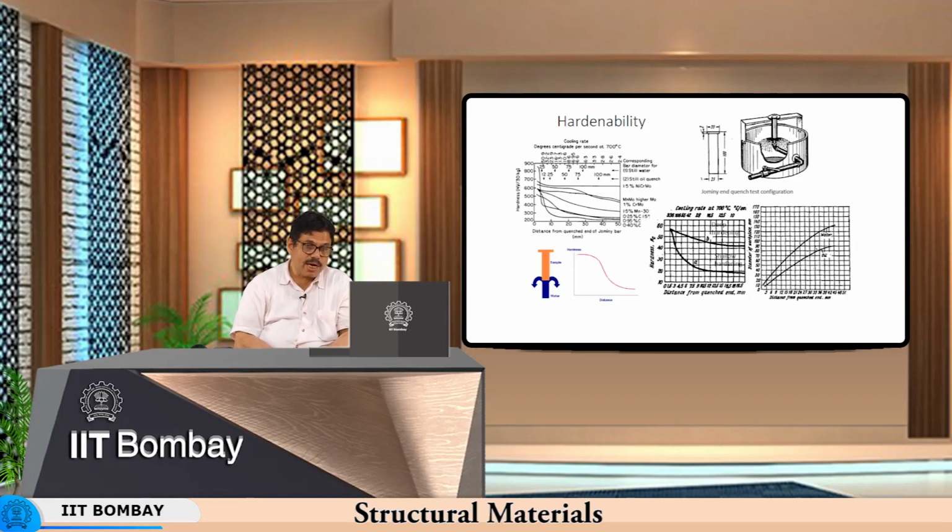So, the hardenability of alloyed materials where you have added manganese, molybdenum, chromium molybdenum, and 1.5% nickel chrome molybdenum is much higher. Here, practically throughout the entire length of up to 50 millimeters, the hardness remains the same. If this Jominy bar has a height of 100 millimeters, then even if you go to halfway, the hardness is practically the same.